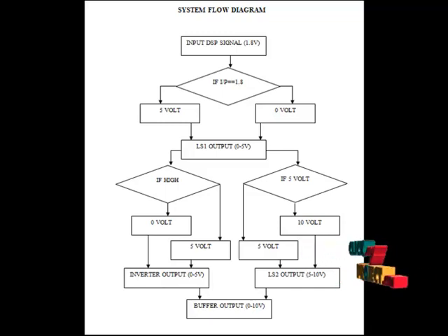Special attention is given in the layout to isolate the high voltage operating circuits from the regular voltage paths. Also, wide top metals are used to route the high voltage supply, the high voltage ground, and the output nodes from the core to the pads to minimize the parasitic resistance and support high dynamic current through this path. In comparison with previous high voltage transmitter designs using CMOS devices, the core area including the output driver and the two level shifters has been dramatically reduced.